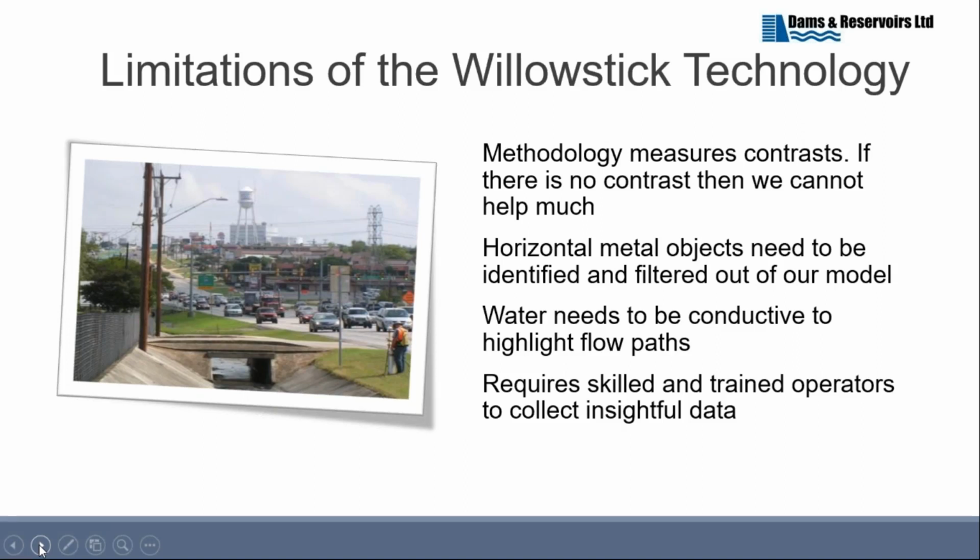We're able to send the results back to Utah. They look at the results while the teams are asleep, and they can redirect the survey on a day-to-day basis. So we can almost tell you in real time what is happening within the dam. And we can move the electrodes to the best advantage to get the best from the survey. And so it's a very useful thing, really, to have the time difference and have people on hand to look at the results as they're coming in.